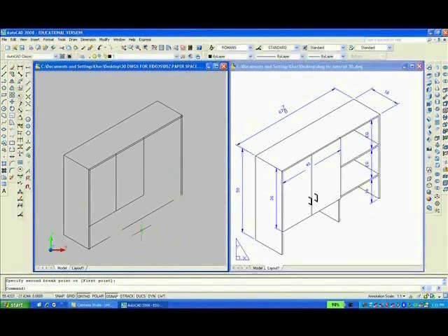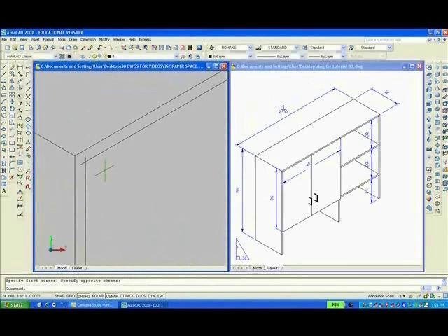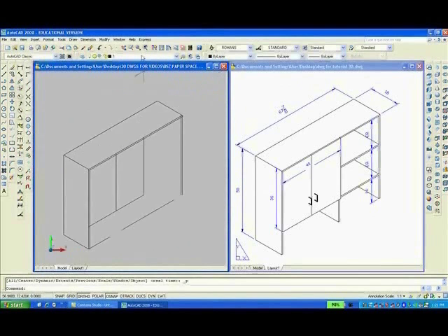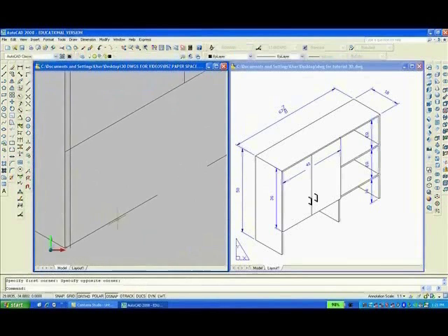Because now we want to zoom in and fillet the intersections. Zoom previous, zoom window, TR, enter, trim from that line into that extra bit, and trim or fillet here and here.